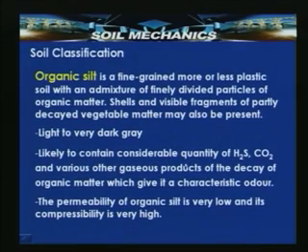Basically, the color of this organic silty soil varies from light to very dark grey, and it is likely to contain a considerable quantity of hydrogen sulfide, carbon dioxide and various other gaseous products of the decay of the organic matter, which give the soil a characteristic odor.